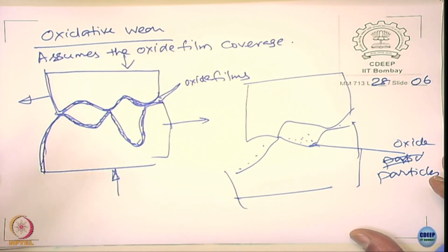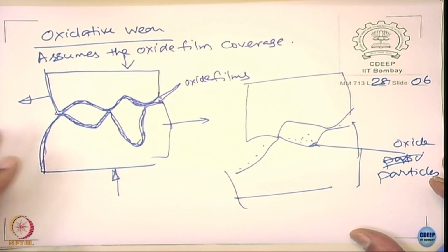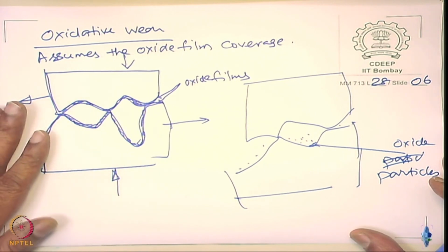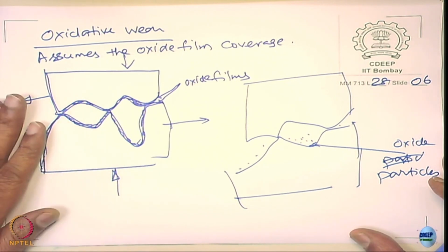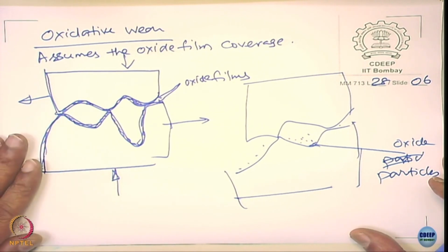So you should have some broad idea about what is wear, what is fretting, and what is fatigue, right? In fatigue also there is vibration and a load, but there is no contact interface; it all happens because of the mechanical deformation.